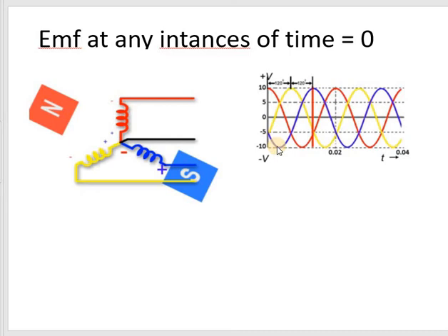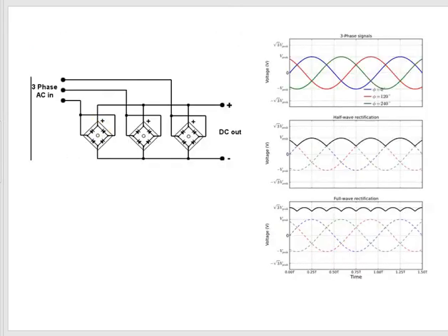If the load is not 0, you cannot design the system in such a way. The delta connection is not possible. A three-phase system is symmetrical if each load has equal impedance value, the load impedance of each phase has equal phase angle, volt and current values are equal for each phase, and the displacement is about 120 degrees apart from each other.